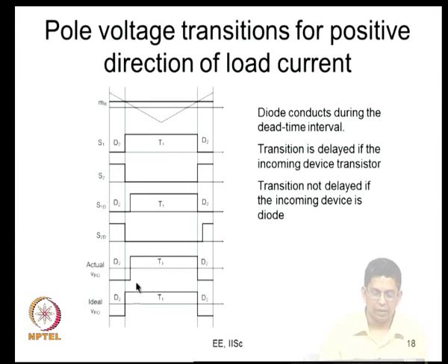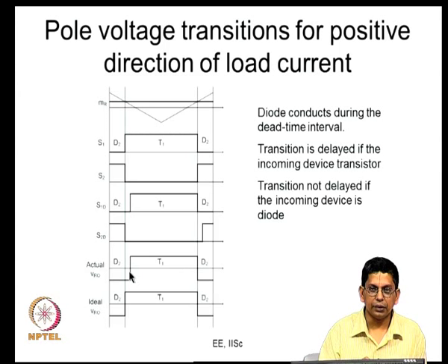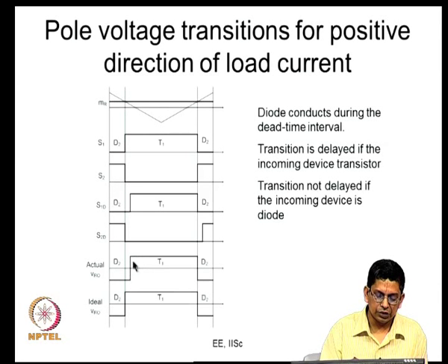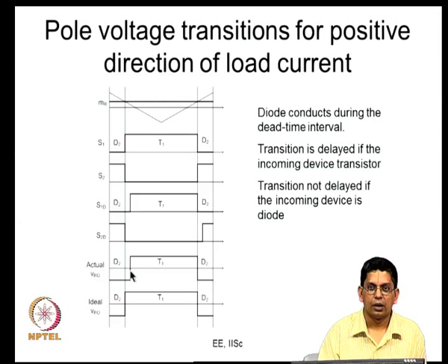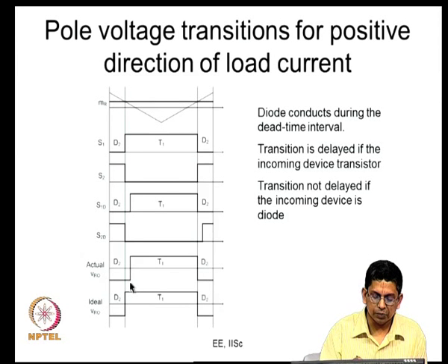So, what are our assumptions here? We are saying still that we are drawing this by a straight line, is it all right? Yes. What we are saying is this is the so called voltage rise time. The voltage rise time is still much less than the dead time, and that is the reason why we are representing this by a ratio.